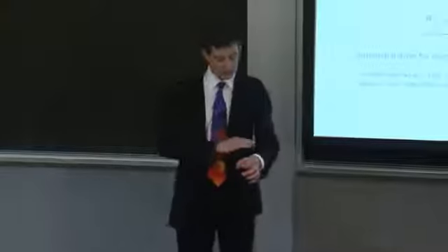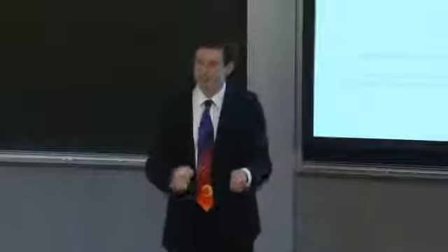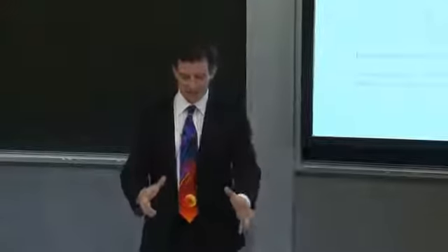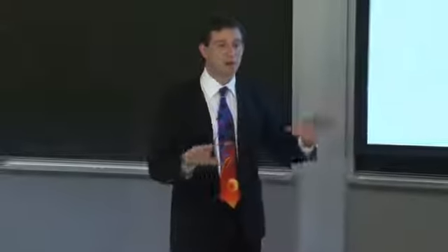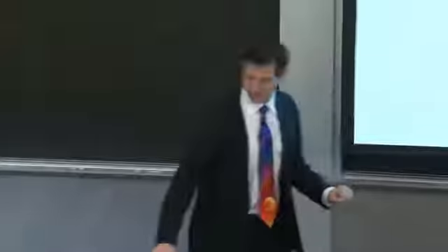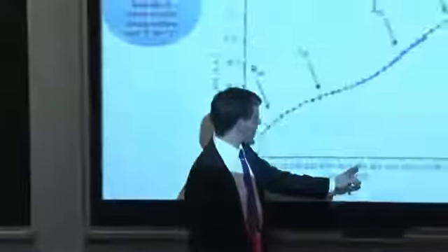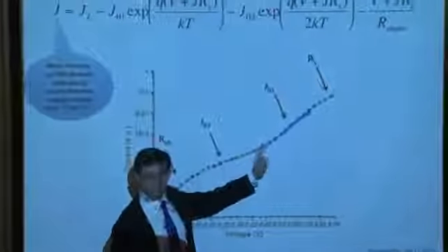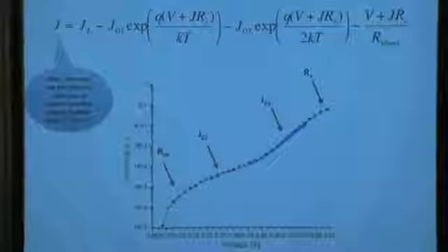I might be able to divide that heat measurement by voltage, so I know the applied bias voltage to my device. I take my power, divide it by the voltage, and I get the current as a function of XY position. So I can map out my dark IV curve at any arbitrary bias voltage condition. Let's say I want to do the measurement at 0.4 volts forward bias. I apply 0.4 volts across my device, and I just measure the heat distribution.